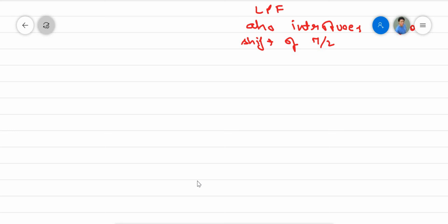The problem with the ideality is that it is non-causal, right? So we will move ahead with the ideal filter and then tend towards the point such that we make a filter which can be realizable, right? So we can write a function Hd(z), which is defined from n equals minus infinity to infinity, hd(n) z to the power minus n.